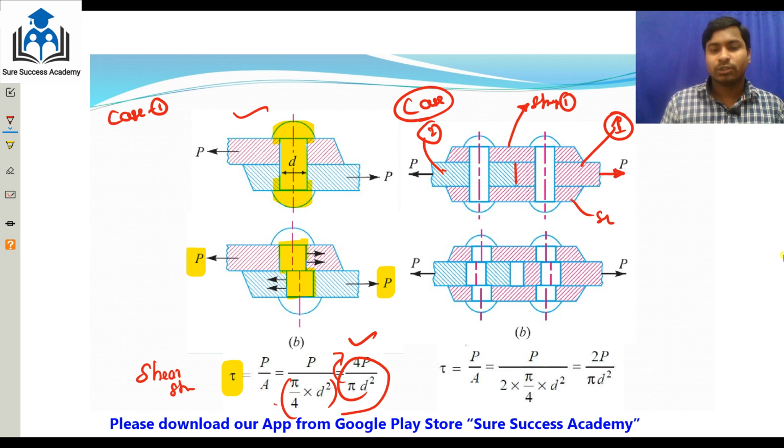Due to this applied force, what will happen here? The plate is parallel to the cross section, parallel to the applied load. This is the tangential area, the cross-sectional area, and this is the resisting area. Each rivet will become three pieces: here one, here two, and three pieces. But the resisting area will be two times. If you apply the load, it will fail here and fail here. So you can say that the resisting area is two times.